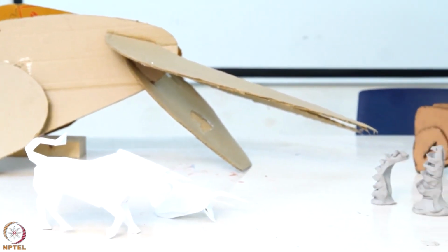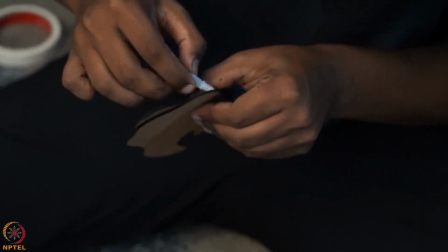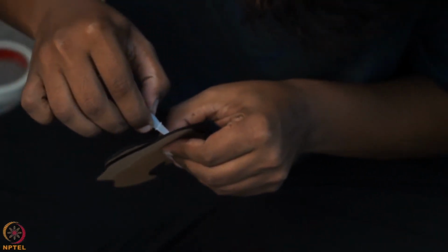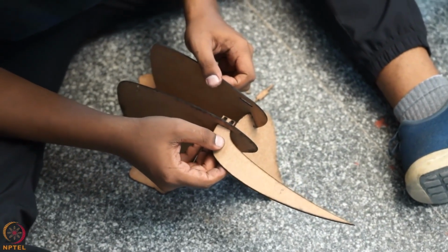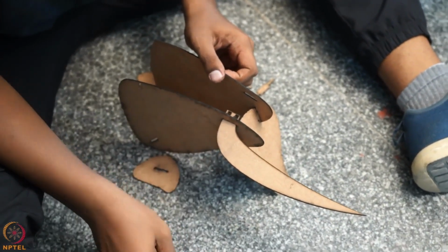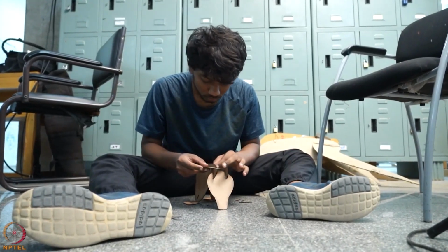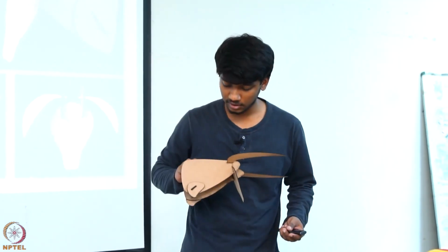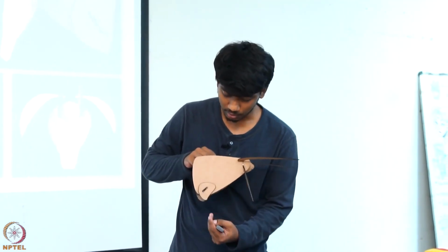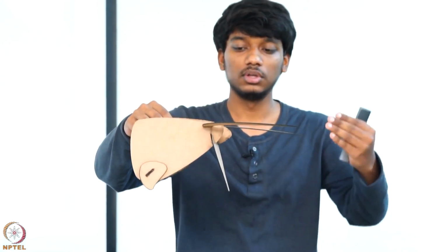After this, we had to do laser cutting in MDF sheet and make a structure from it. The main complexity behind doing this was that we could only use plates and we had to intersect them. We can't fold them. This was the first laser cutting that I did, and as you can see, the behind elements are a little smaller. Then the horns are a little tilted inward.